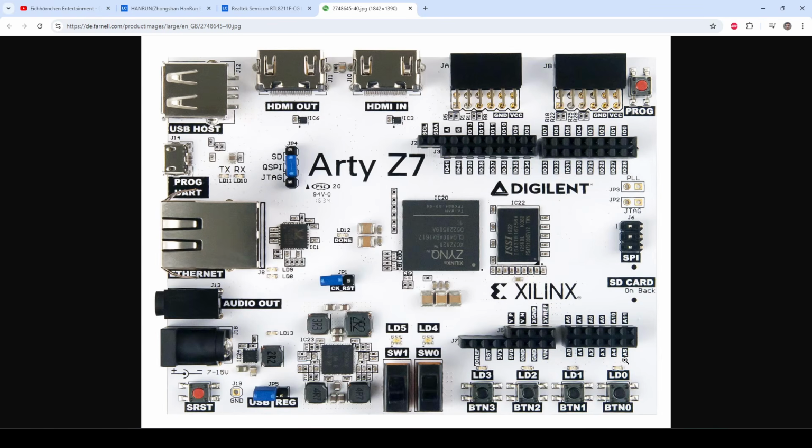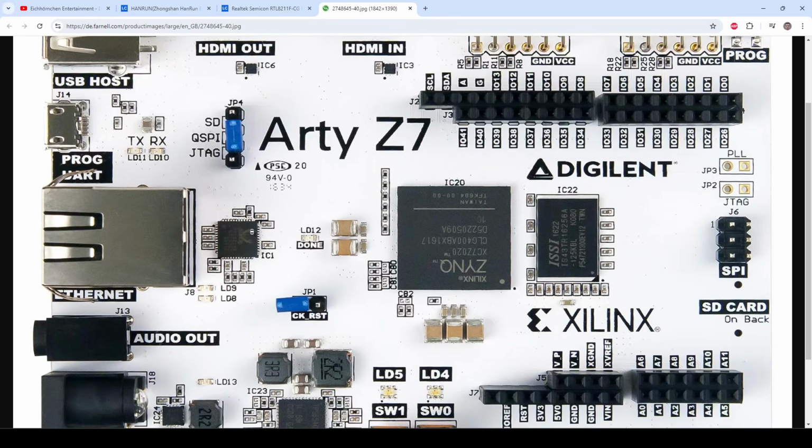To get some ideas, we can also look at other boards, how other people have successfully implemented MagJack connectors and Gigabit Ethernet PHYs, for example the RTZ7, where we looked at briefly the schematic earlier. We have the physical layer, where my cursor is on the left hand side, very close to the MagJack connector, and the MAC, which is integrated in the Zynq system on chip, is on the right hand side, so you can get a sense of scale and placement and how you typically want to place these parts.